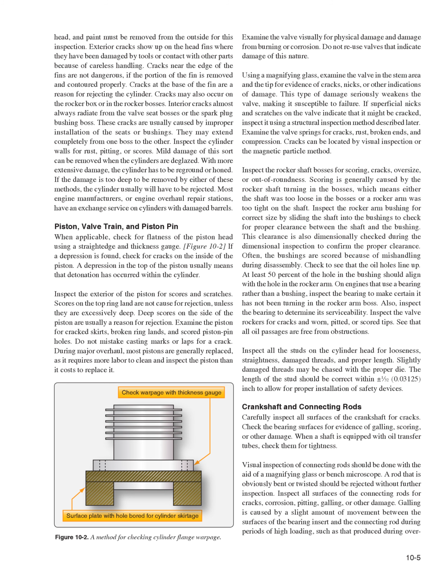Cracks may also occur on the rocker box or in the rocker bosses. Interior cracks almost always radiate from the valve seat bosses or the spark plug bushing boss. These cracks are usually caused by improper installation of the seats or bushings. They may extend completely from one boss to the other.